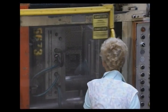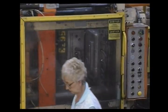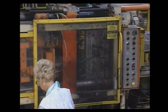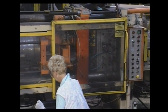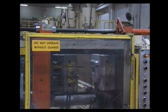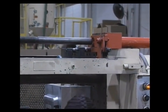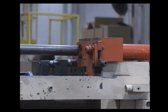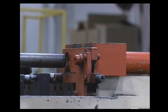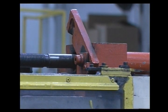Injection molding machines are designed not to operate unless the front and rear safety gates are closed. This limits access to the platen area while the machine is in operation. A safety drop bar is required on injection molding machines. It drops down between the platens when the safety gate is open, so that the machine cannot close upon a person. This is in addition to other hydraulic and electrical safety systems.